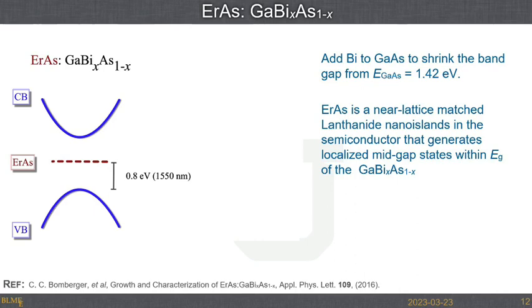Everything to do with an optical fiber, everything to do with fiber optic communications uses 1550 as the wavelength for all of that. So if I want to use existing technology and existing fiber optics technology, I need to figure out how to create my radio such that it's going to respond to that photon energy. So if all I can do with the bismuth is get the band gap down to 1 electron volt, that's still not enough. I'm actually able to put these states mid-gap such that the peak response is going to be right exactly where an erbium-doped fiber amplifier, which is the laser that people use for all of this, will operate. So this is all materials engineering here.